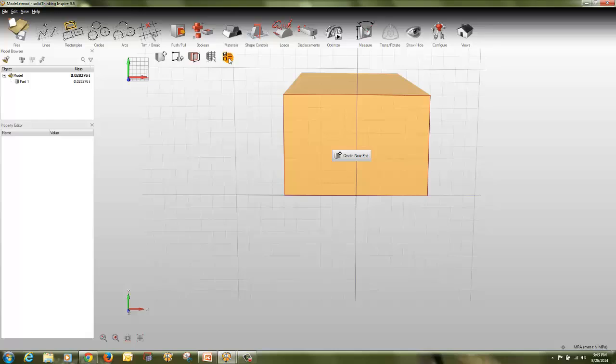While sketching, you can apply geometric relationships such as tangency and perpendicularity to lines, arcs and circles using sketch constraints. As you sketch, Inspire automatically applies many sketch constraints for you. This behavior can be disabled using the preference window, which can also be used to modify the default angle measures for certain constraints. When you are finished sketching, right click to exit the active sketch tool. At that point you will still be in sketch mode and may either select another sketch tool, click on a sketch curve to edit it, or right click a second time to exit sketch mode entirely. When you exit sketch mode, the push-pull tool is automatically activated so that you can immediately push or pull your sketch into a solid.